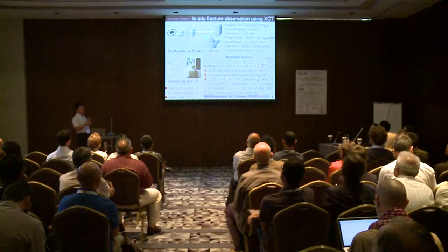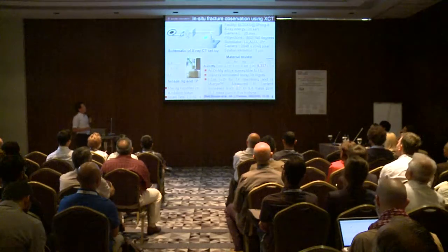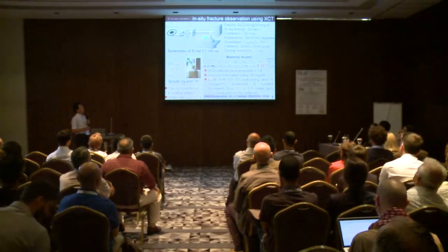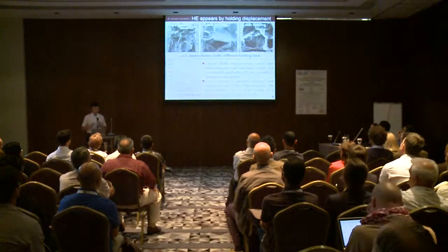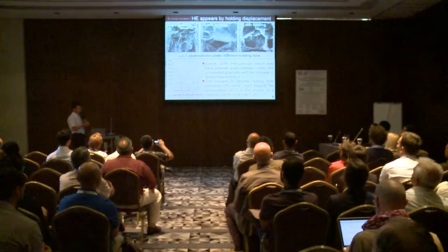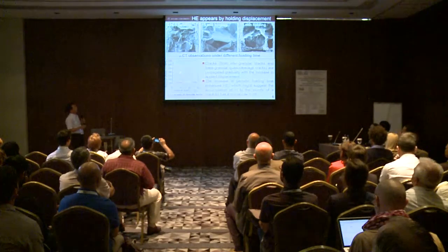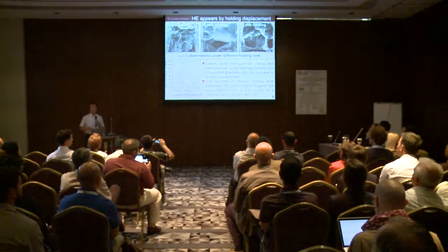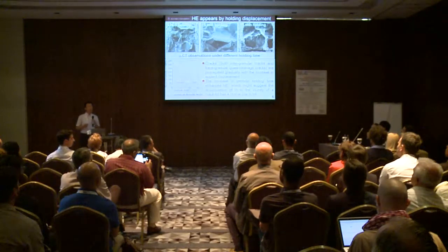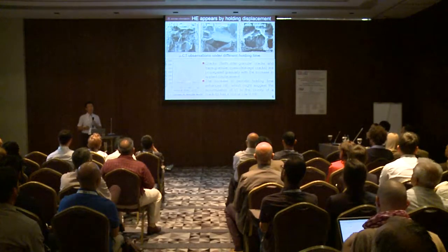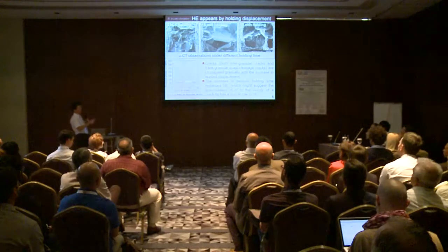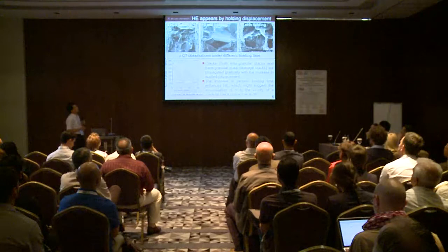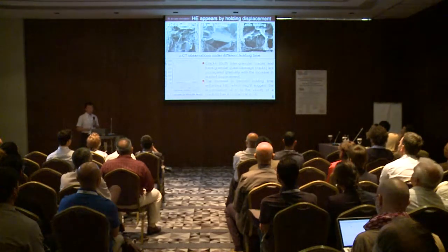According to a past paper, hydrogen concentration increased by more than 45% by simply applying the EDM technique for sample preparation. We are now looking at stress-strain curves together with SEM micrographs. Fundamentally, we don't observe hydrogen embrittlement if we don't interrupt the tensile test. But if we interrupt the tensile test periodically in this way, then we observe hydrogen embrittlement.